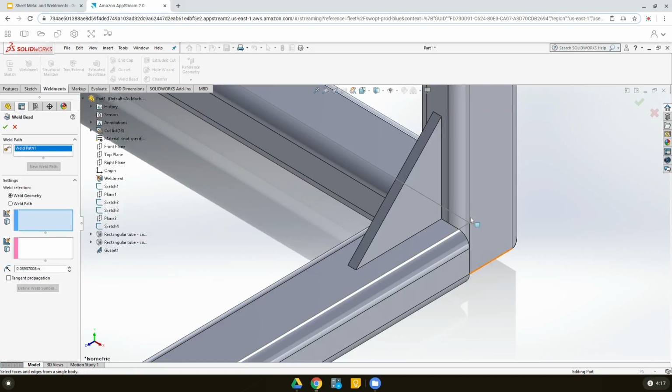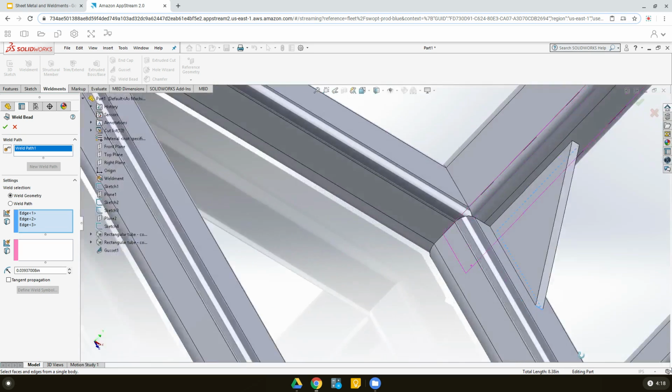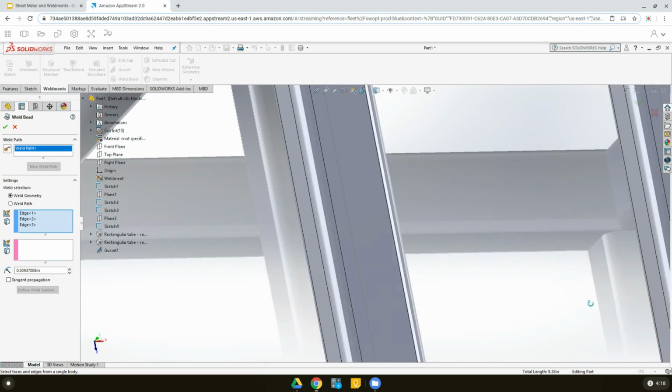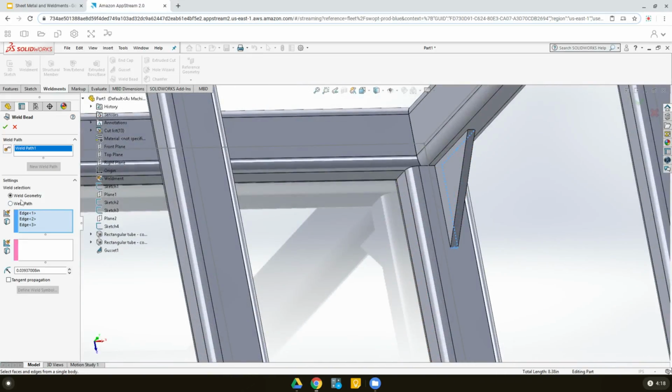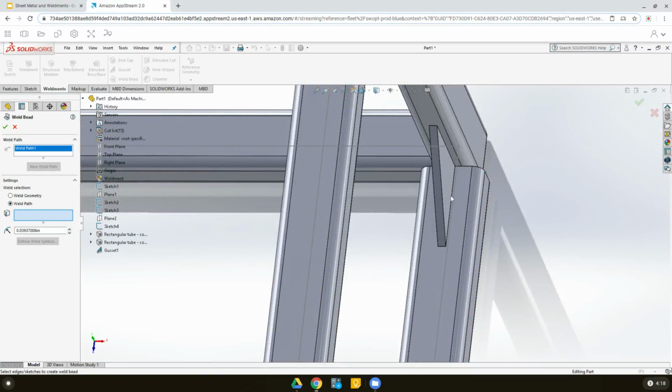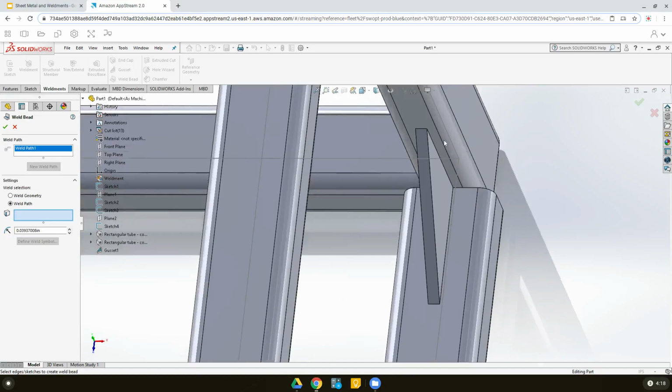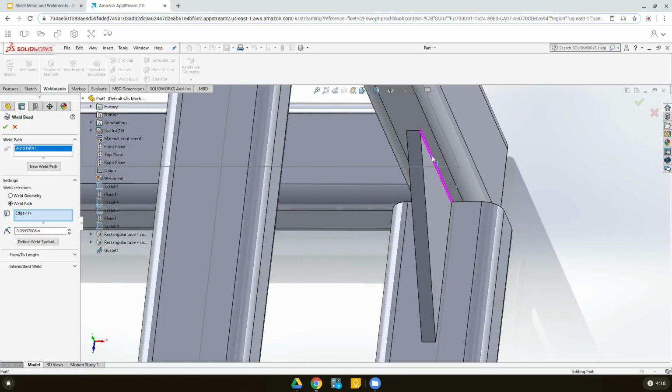select the gusset edge. So we're going to select this gusset edge, we can select all the gusset edges, right? So I'm just going to go around on both sides, gotta be really careful. Let me try again. Yeah, I was trying to choose weld path, but apparently I selected from weld geometry to weld path, and I'm going to click on okay.